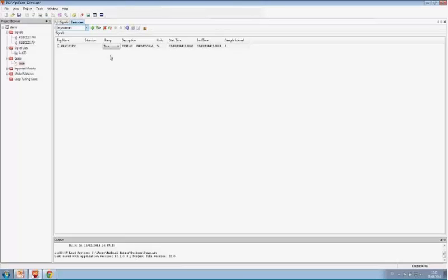Okay, so now we have selected the input and the output. Of course, if this was a MIMO case I was showing, I would have selected more than one output and more than one input. Or if you want to have some, let's say, disturbance input to improve your model, you could choose them as well. But for now, we only have one input, one output.